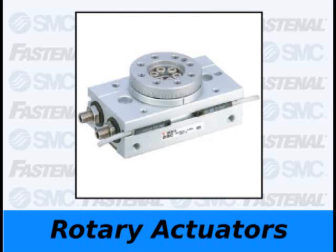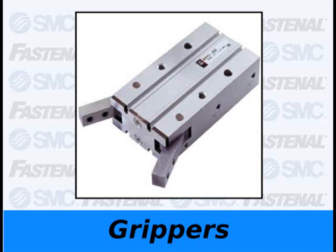In addition to air cylinders that go in and out, there are rotary actuators that turn left and turn right. These aren't always visible, but if you see a table turning left and right, you can bet it's driven by a rotary actuator. Other actuators are called grippers because they have 2, 3, or 4 fingers that open and close to hold on to something.